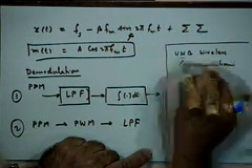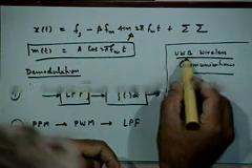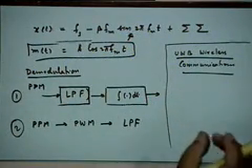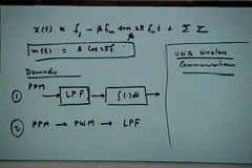Right, where you are not transmitting over very long distances. Maybe you are designing a LAN in a limited area, or actually it is presently more used in defense applications of some kind. Basically, you do not have a carrier once again, you are transmitting baseband pulses in air, very narrow baseband pulses here, which is very difficult to do because the corresponding antennas become very difficult to design, efficient antennas.